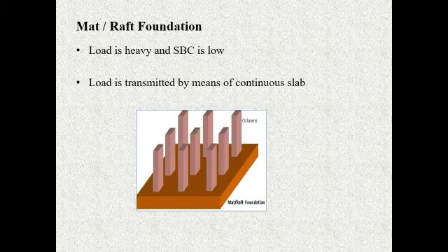And the mat and raft foundation. These types of footings are used where the soil bearing capacity is low but the structure will have a heavy load. In this footing, the loads are transmitted by means of a continuous slab.